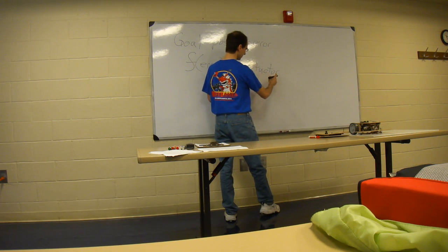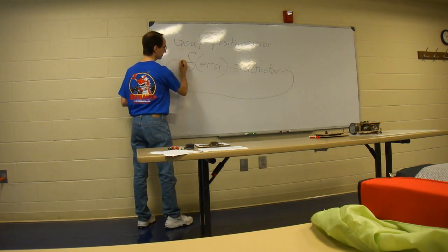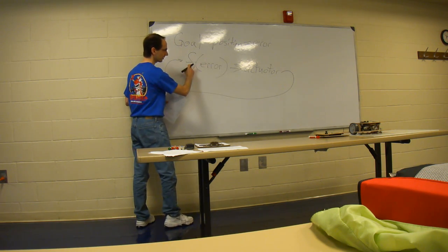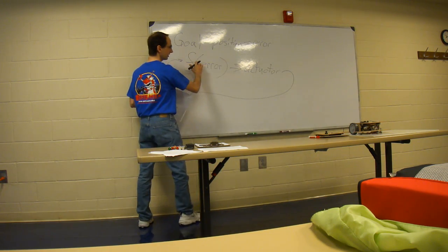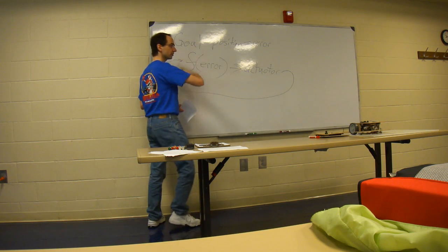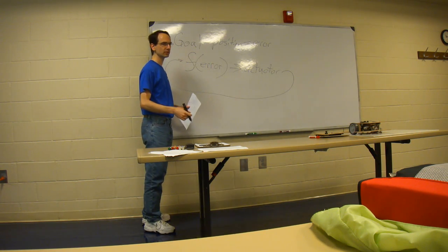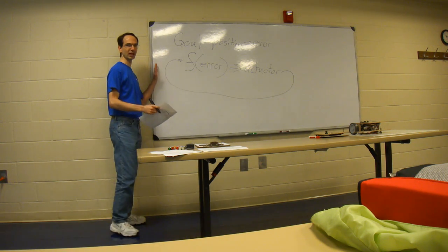The actuator is going to change our position, which we're going to then recalculate the error, and that's going to go back into the function. Back in, the actuator makes a change. We see the change, make the change, see the change. It's just an infinite loop, and it keeps running forever until we tell it not to. And that is the basics of a feedback loop.